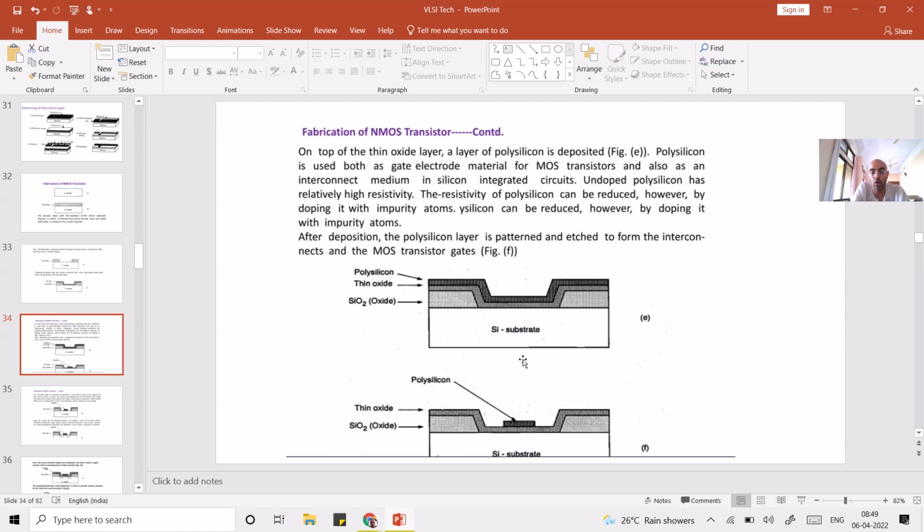As I have shown you in the very initial lectures, these devices are very small. And if these devices go to the micron level, then controlling the source and the drain regions becomes very difficult. So you want a process in which the source and drain regions are formed automatically in that region only. There should not be any chance of forming them in misaligned regions, or other regions which you have not desired. So that is why you use polysilicon. Polysilicon gives you the advantage of self-alignment, and because of this, very small geometry devices are possible.